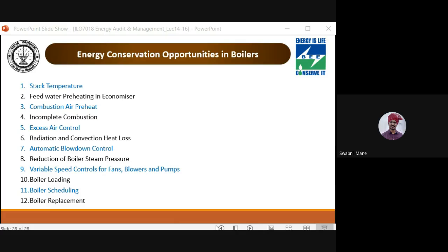pre-treatment of the water. So water gets demineralized, otherwise minerals will get deposited on the inner side of the boiler. After due course of time, this water will lose its tendency, and this material will get deposited on the inner side of the tube. To avoid that, we require the water that is present in the boiler to be thrown out to the atmosphere. This is called blowdown.